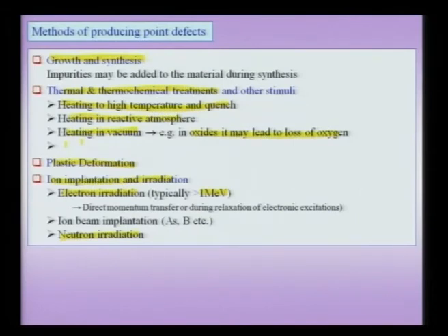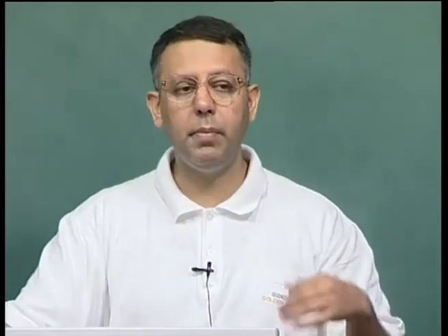There have been electron microscopes, for instance, which have a capacity of 1.25 million electron volts, and with such electron microscopes we have to worry about the electron irradiation damage on the specimen. In other words, if I am analyzing a thin specimen under one of these very high voltage microscopes, then some of the defects I may be seeing are actually not the original defects present in the material, but have been produced by the electron irradiation damage. So, if I see some such defects, I have to confirm them by putting such a sample in a rather low voltage microscope to confirm that this is not damage which has been produced by high voltages.